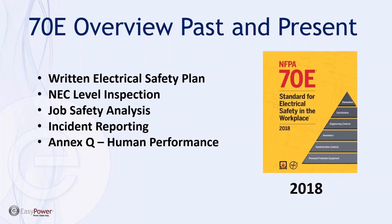2018 brought even additional support to that. One of the big changes in 2018 was the addition of NEC level inspections. Interestingly, the way that language is written into the 70E standard, it speaks to inspections of just new work and new equipment in the building. Fast forward into our 70B requirements, and we're going to find that now we look to inventory and inspect all equipment, as we merge these standards together over time.